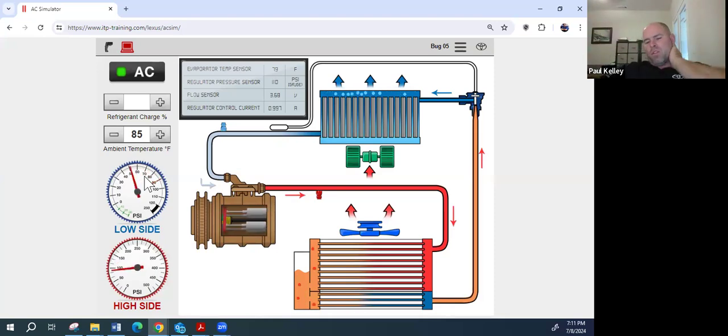That doesn't happen if there's no moisture. The problem is there's moisture in the air we pump into the tire, because the compressor is pulling from the atmosphere and its humidity. If you did it with nitrogen, you wouldn't have that big of a temperature swing, but it's a major swing when it gets hot. So if it was just the hot side spiking way up, I might consider going with air.